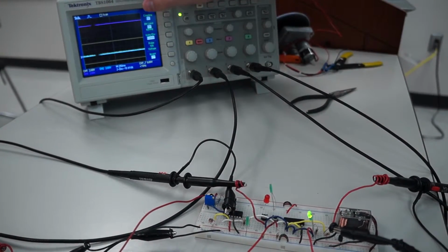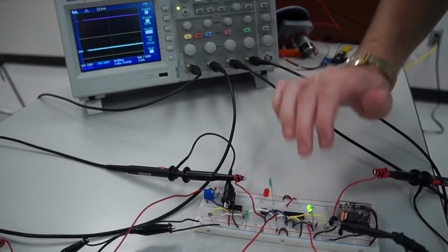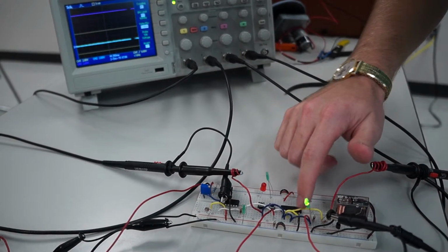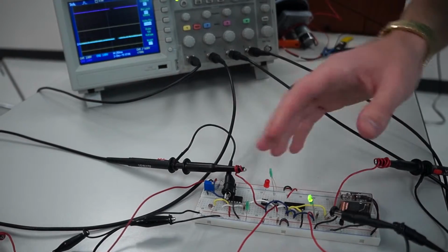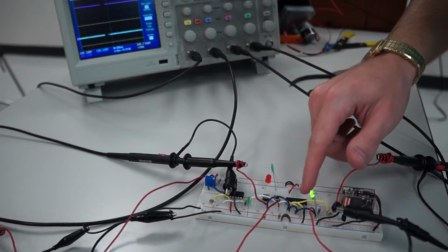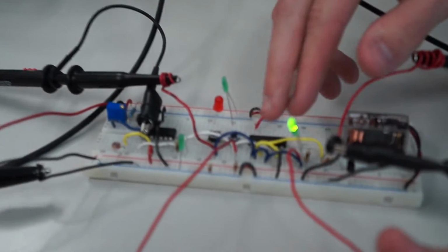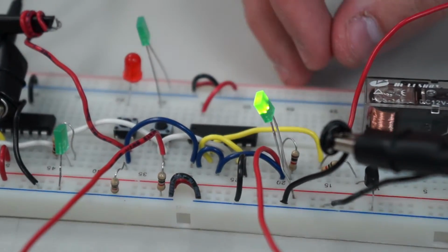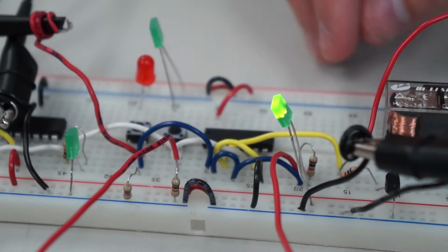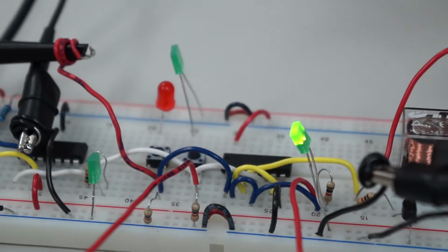Now we know there's a problem with our Q, or subsystem 2. We can observe and look at our schematic and see if we have all of our wires plugged in correctly. And then if we have all this correct, then we know it's our RS flip-flop that's the problem. So we want to replace that and see if it works correctly.